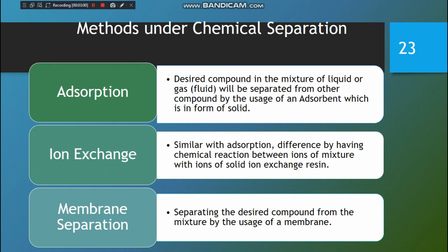The techniques used in ion exchange so closely resemble those used in adsorption that for the majority of engineering purposes, ion exchange can be considered as a special case of adsorption. So in ion exchange, certain ions are removed by the ion exchange solid. Since neutrality must be maintained, the solid releases replacement ions to the solution.